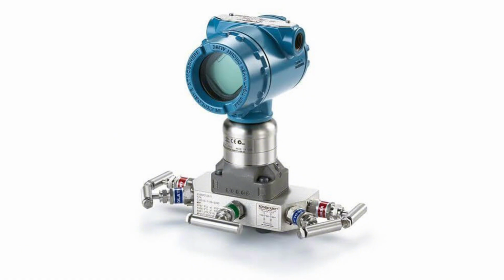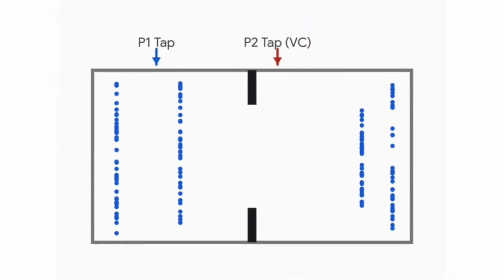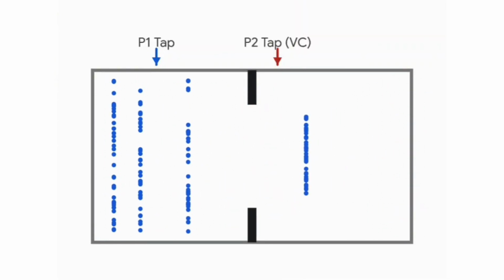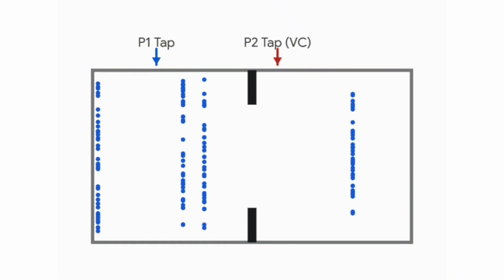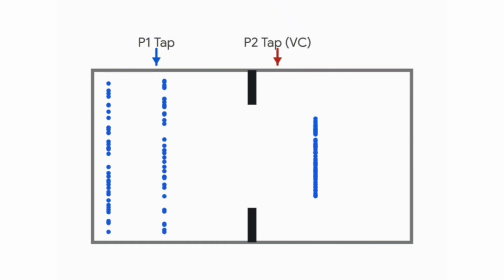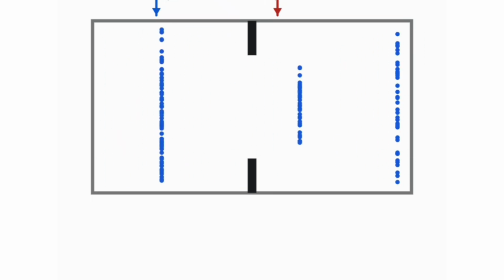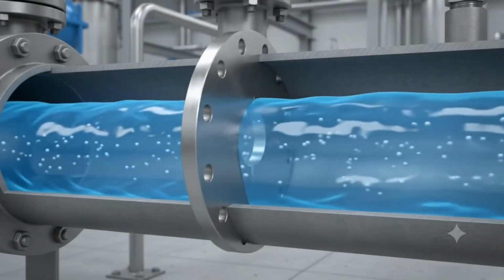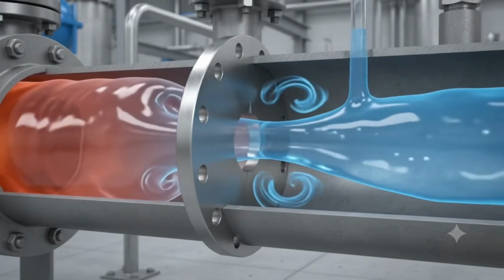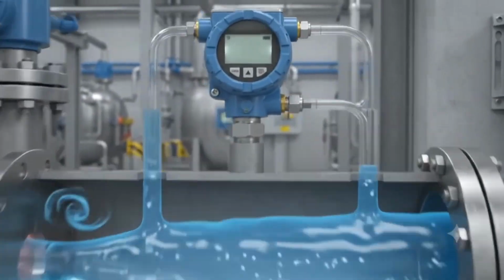Practical considerations. Advantages. Simple design with no moving parts, low initial cost, standard calibration standards (ISO 5167, AGA 3), and wide suitability for high-pressure, high-temperature applications. Limitations. Causes permanent pressure loss, unrecoverable head loss, subject to edge wear or slurry buildup, low turn-down ratio,